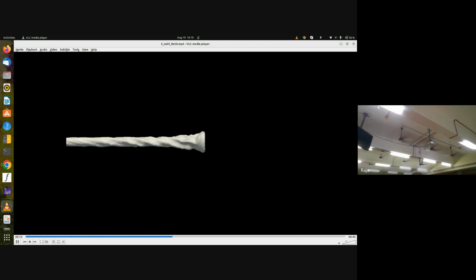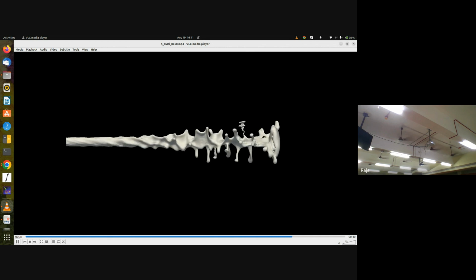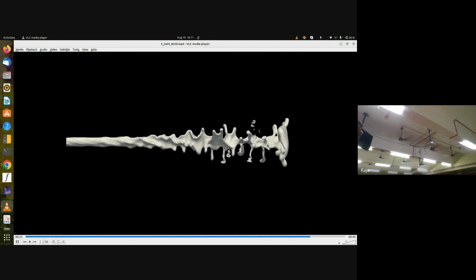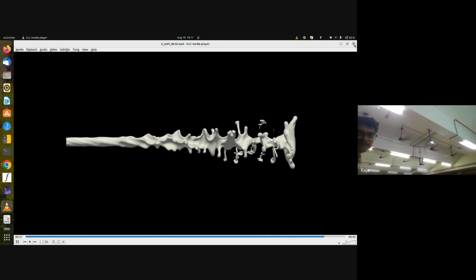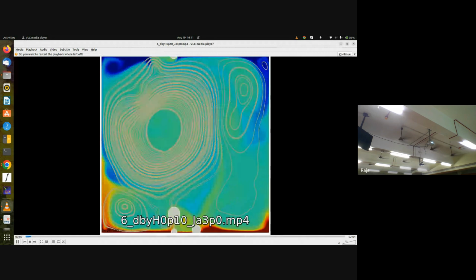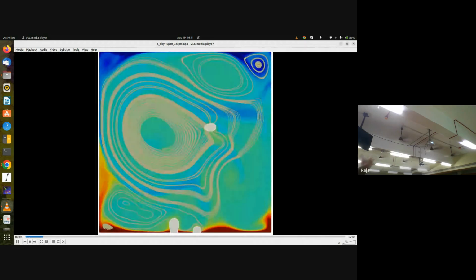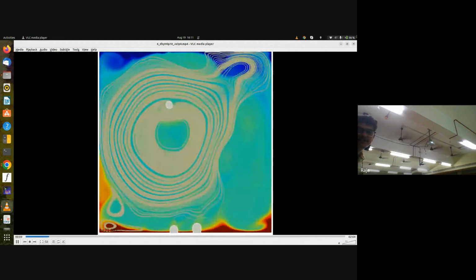Specialized modes of instability develop on these spinning jets, and they start getting detached. Coriolis effects come into the picture, and locally they detach. And something about boiling and condensation: bubbles are growing and condensing inside a thermal environment. What will happen to them, and what kind of large-scale structures do they create?